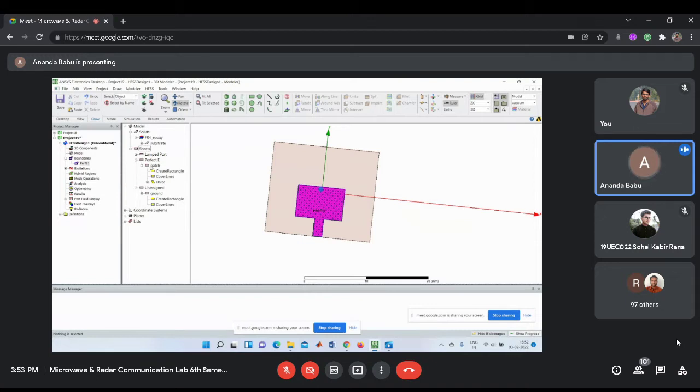so here this one, then we go to the simulation. This is what you require first: the patch, the boundaries and the excitation. All these are the three steps. First the patch, boundaries and excitation. Then go for the simulation.